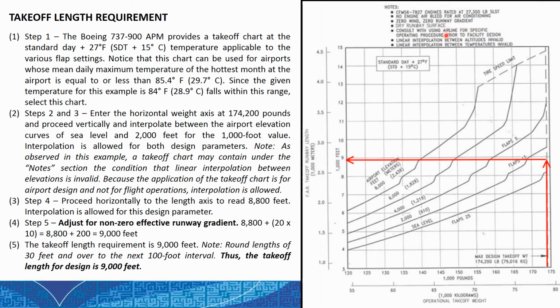So if there is a runway gradient, we have to adjust, because the chart is for zero effective runway gradient, and also the landing length requirement chart.